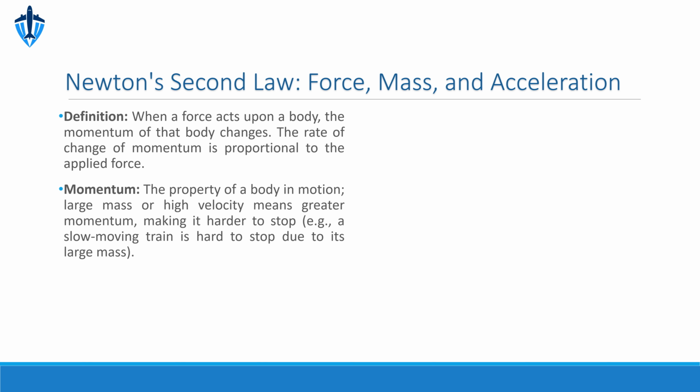Now let's continue with the single movable pulley, which offers a different operational advantage. This pulley acts like a second-class lever, where the effort arm spans the entire diameter of the pulley, while the resistance arm is just the radius.